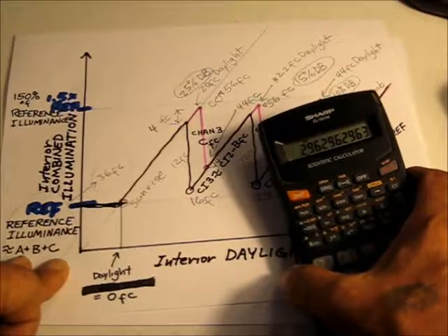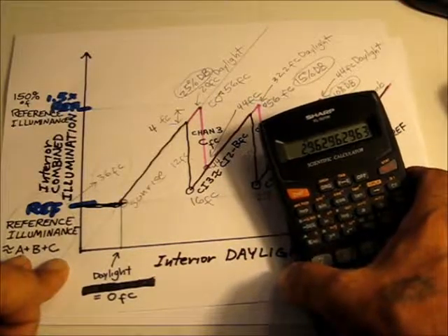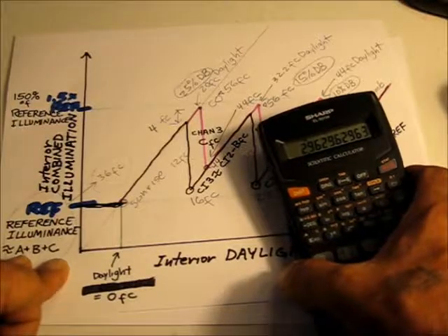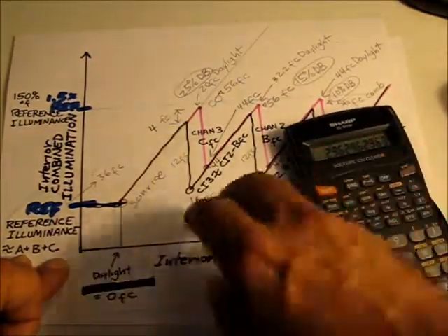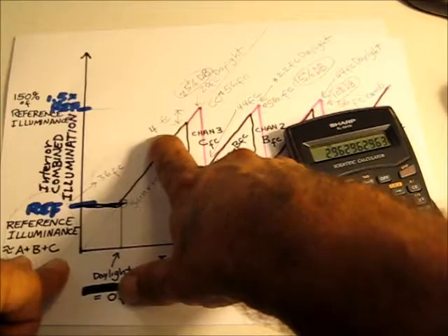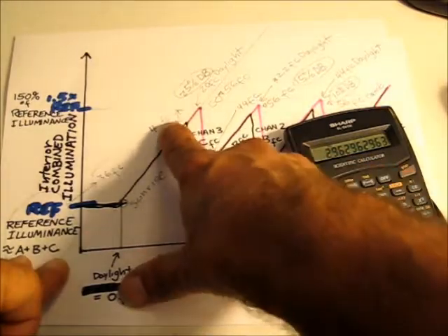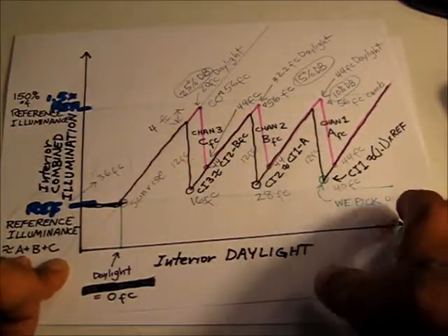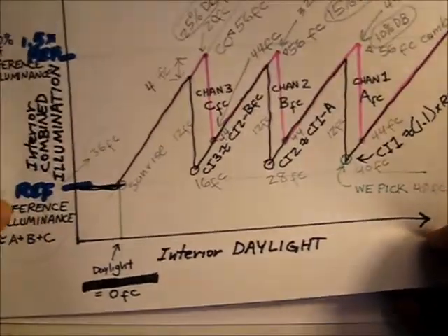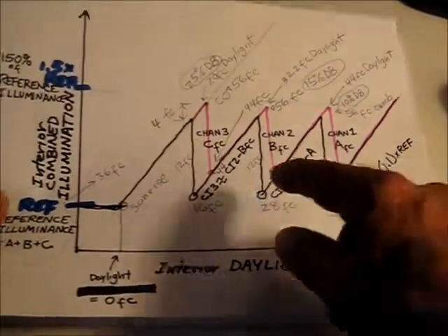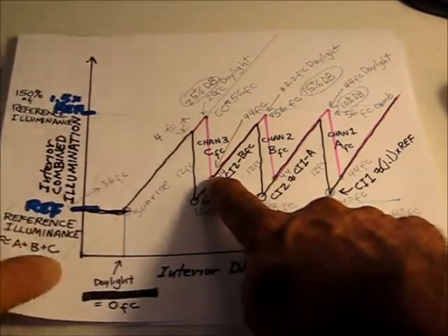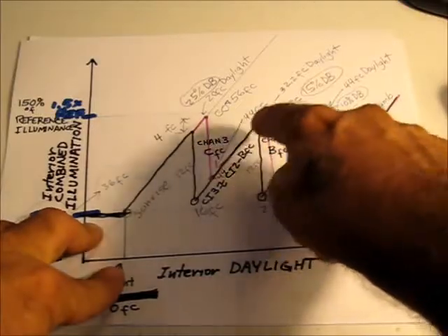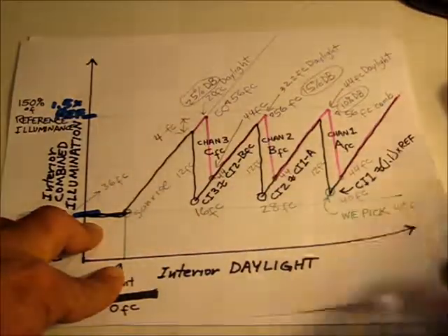If we round it up to 3, that's still too close. So we round it up to 4. Okay, and that would be the minimum deadband foot candles that we are programming for. Now in the last example, we just stuck with a minimum deadband setting, but you may want these points to drop elsewhere, and we'll cover that in the next module for maximum deadband calculations.